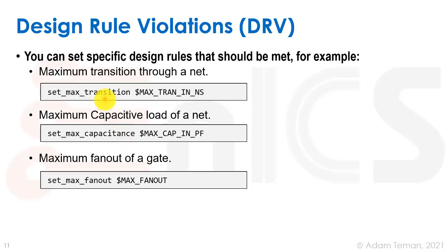Why? Well, remember that when we had our NLDM or our different types of timing models, we always had a table that was made out of transition and capacitance values, and for different points that were checked beforehand in SPICE or some other tool, we had calculations.